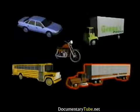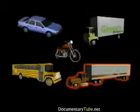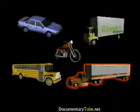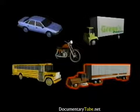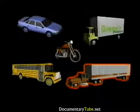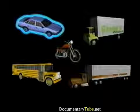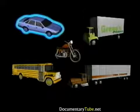In general, the loudest vehicles are in the heavy truck category. As an example, at a distance of 15 meters or 50 feet, a single heavy truck traveling at normal highway speeds can produce a maximum sound level of around 85 dBA. The quietest vehicles are in the automobile category.